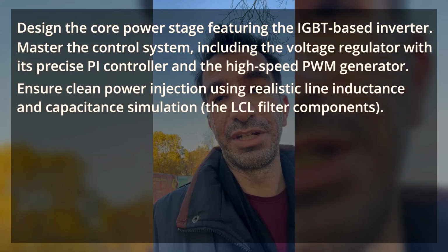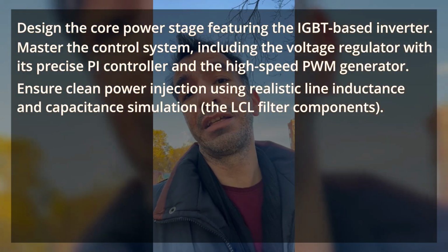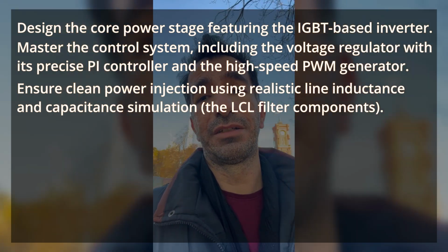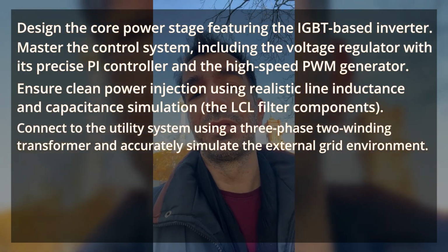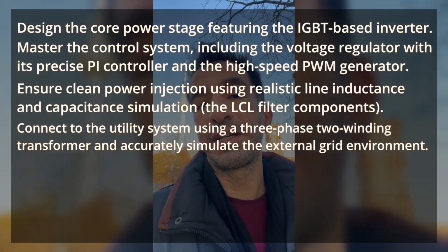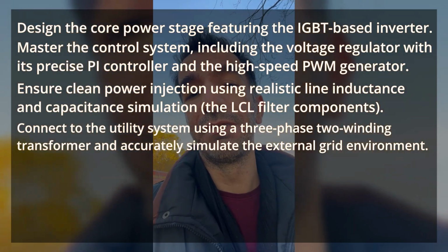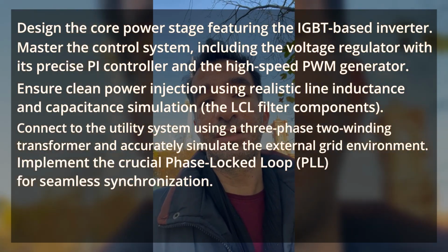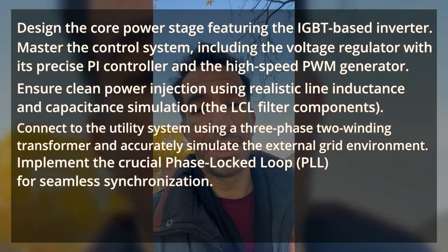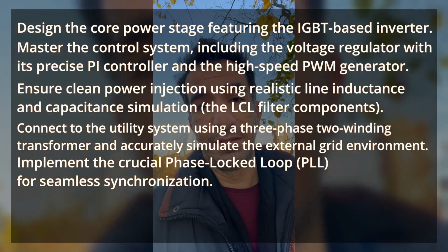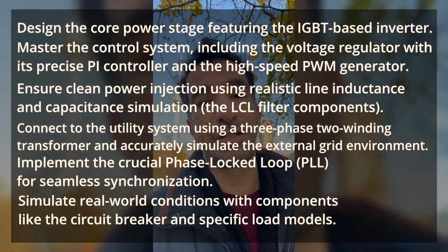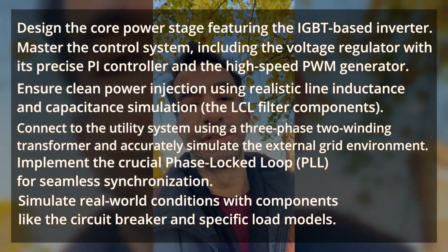Ensure clean power injection using realistic line inductance and capacitance simulation. The LCL filter components connect to the utility system using a three-phase two-winding transformer and accurately simulate the external grid environment, and implement the crucial phase locked loop (PLL) for seamless synchronization. We also have the simulation of real-world conditions with components like the circuit breaker and the specific load models.